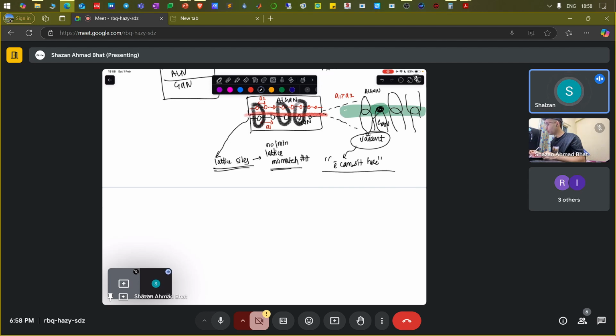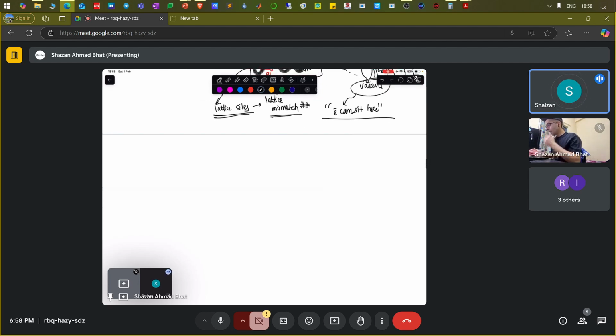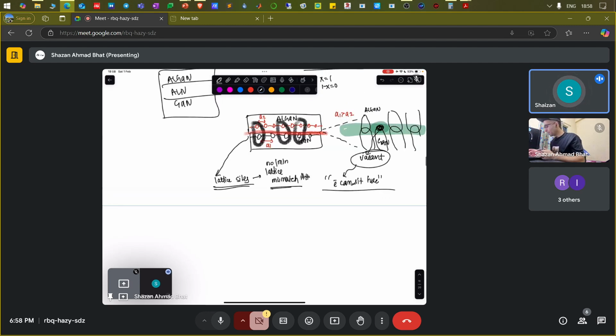That is the important aspect. So you cannot grow an arbitrary material over these particular sites. Okay. Now we talked about these particular things. That means if the lattice constant A1 of GaN is greater than that of AlGaN, then this has to slightly stretch towards the other end.